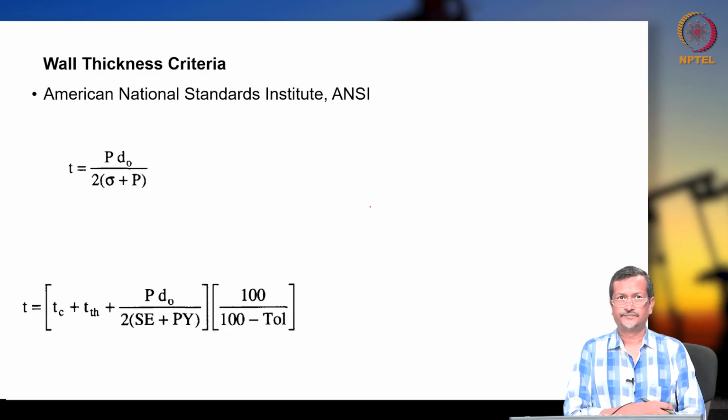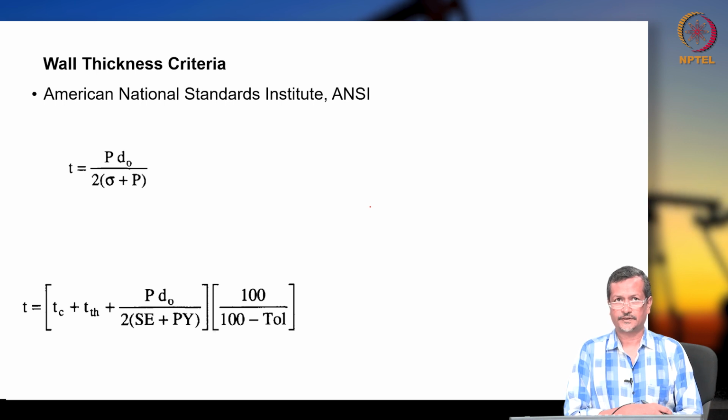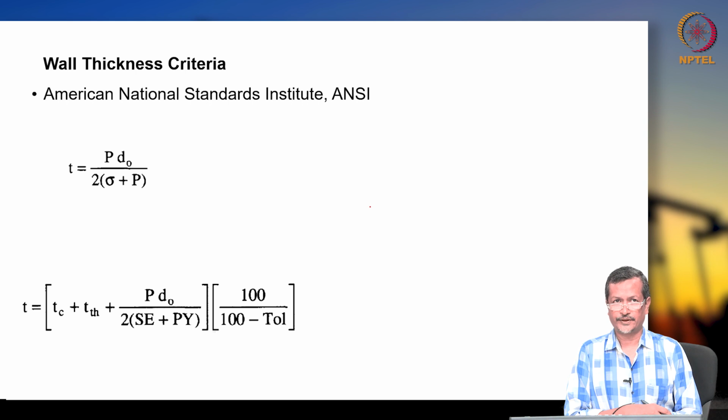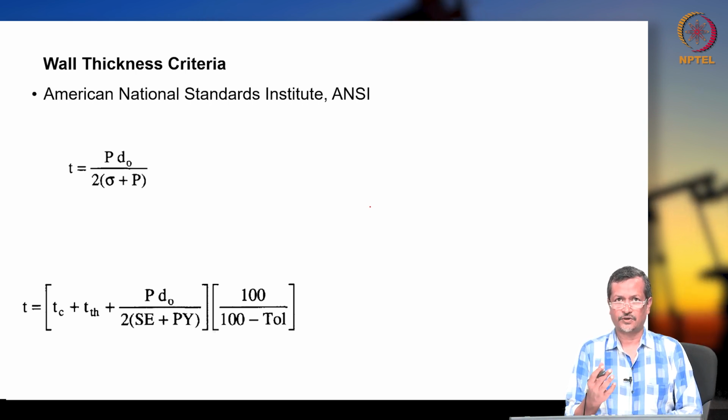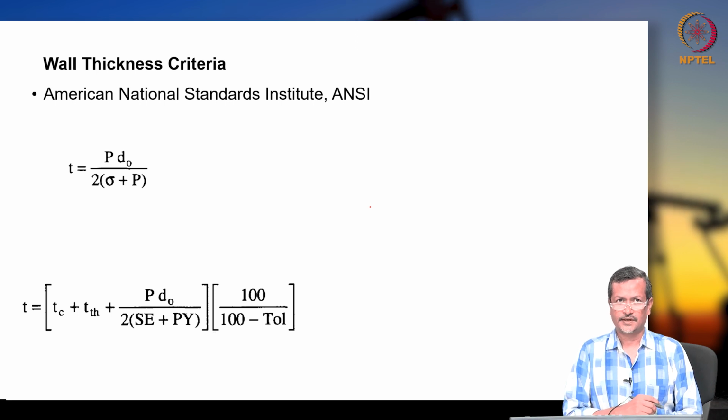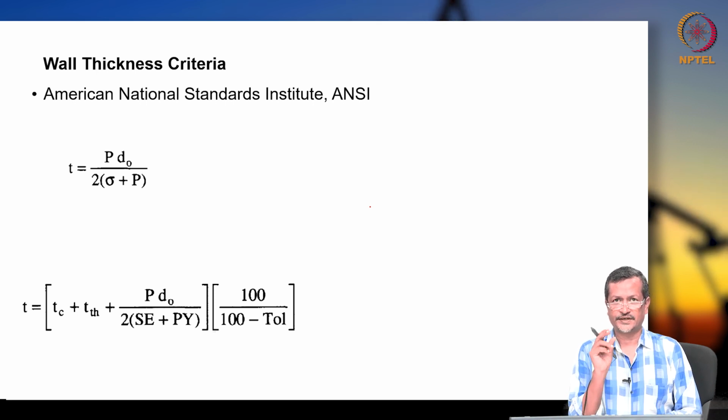Good morning. We already started the topic pipeline sizing. So, when you are sizing a line or pipe, you have to know the burst pressure or hoop stress, you have to understand. Then, what is the thickness? Wall thickness you should consider.